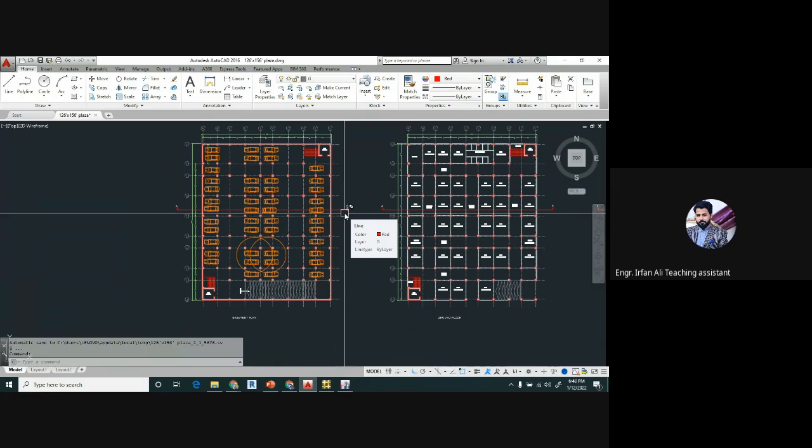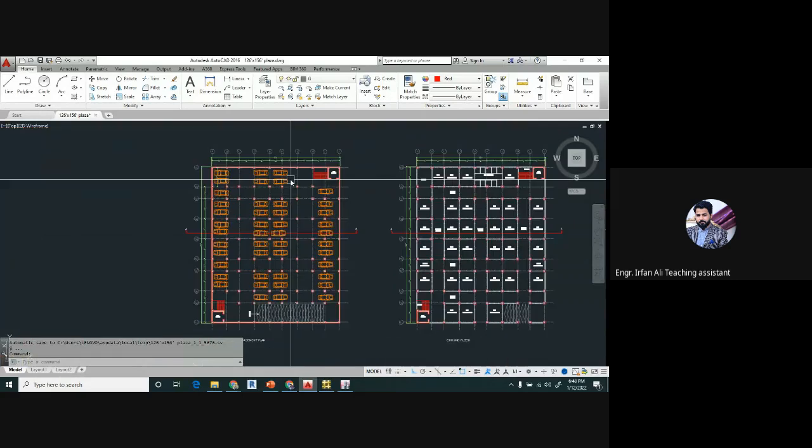But if it is high rise, for example 14 stories, or greater than 15 stories up to 20 or 25 stories, you have to increase the spacing between the two blocks to 3 inches or maybe 4 inches to minimize the effect of pounding. These are the general considerations which we adopt during our design in consultancy.